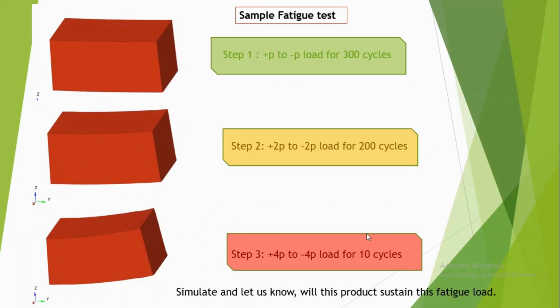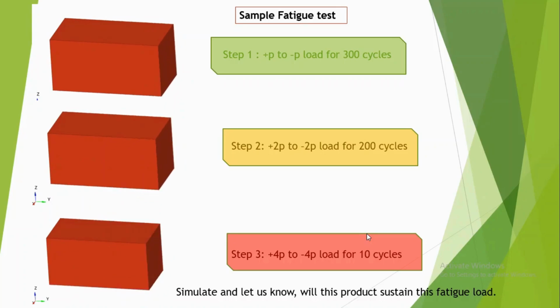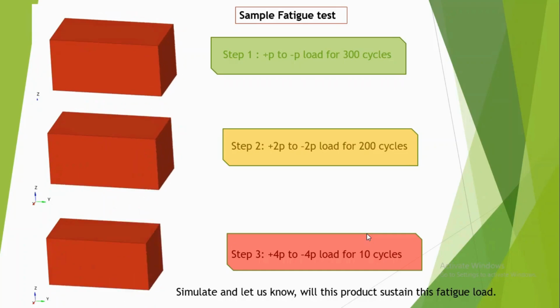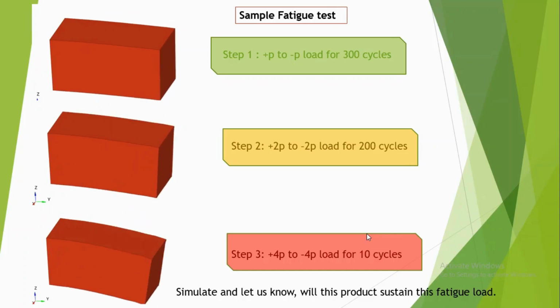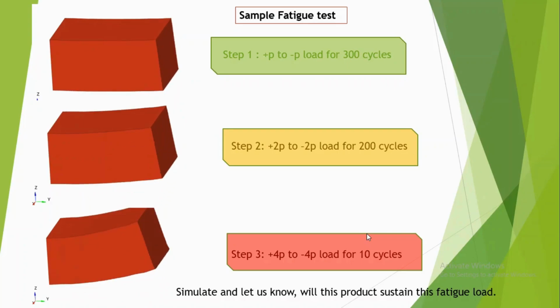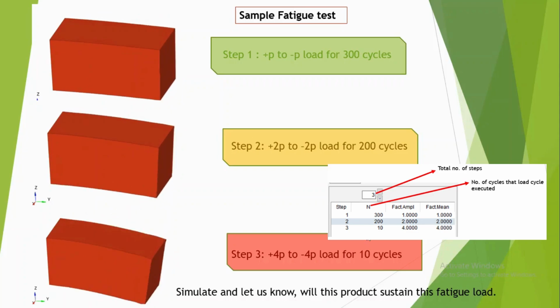And if someone asks you, before even testing, to simulate and let us know whether this product will sustain this fatigue load or not, you need to create the block cycle in FEMFAT to know whether this is above one block cycle or not. If it is above one block cycle, that means your component will not fail under this cumulative damage test. And if it is less than one block cycle, then you can say your component will fail under this cumulative damage test.